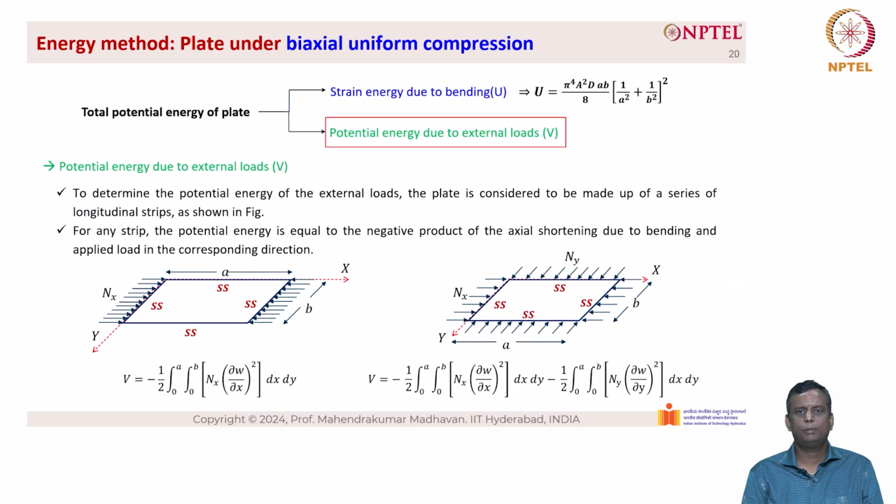Now, for biaxial compression, we have V equal to minus half into integral 0 to A, integral 0 to B Nx (∂W/∂x)² dx dy, minus half into integral 0 to A, integral 0 to B Ny (∂W/∂y)² dx dy. The second term is simply because the plate is also getting loaded in the y direction as well.